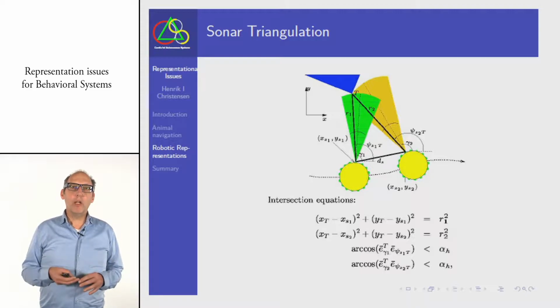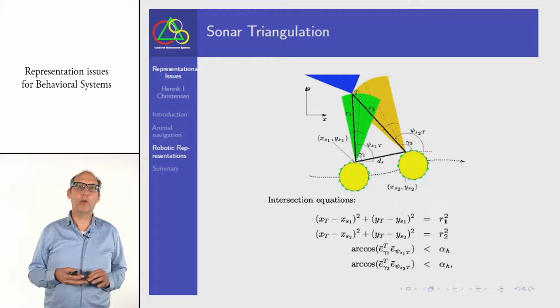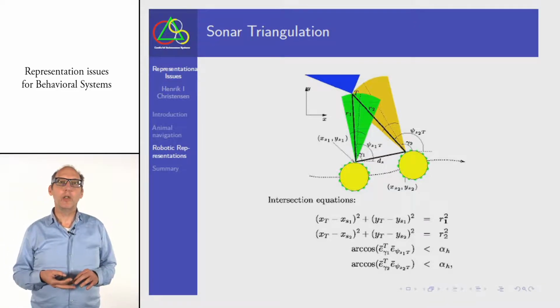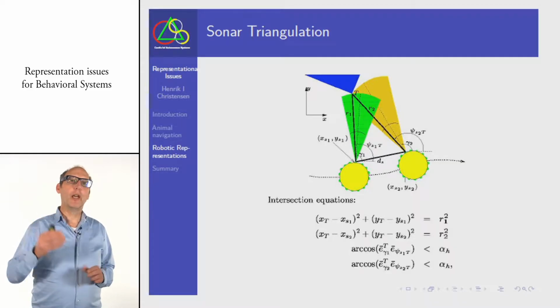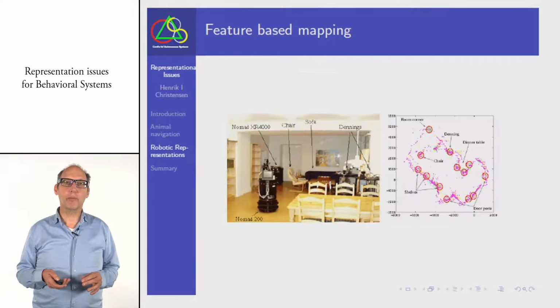Why do you need a little bit of that long-term, short-term memory? So not only one observation, but two observations. Because in principle, if you have one observation, you have only a vague idea of an obstacle. But if you move your robot and you have two observations, and with triangulation, you can get a much better estimation of both the range and the angle of the obstacles. So in that way, by combining a few observations, you can make a much better measurement of your environment.